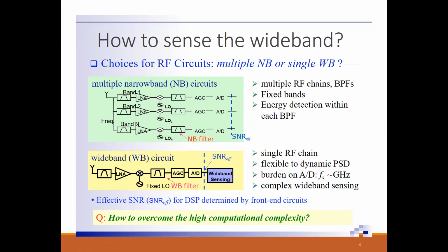You get my point. Even though the user is actually occupying 1 megahertz bandwidth, you think that 2 megahertz of bandwidth is occupied because you are using fixed bands. These filters are not variable. You check for 0 to 1 and you check for 1 to 2, but you are not adapting. So if a particular user is occupying from 0.5 to 1.5, that will induce the spectrum decision both here and here, which is again ineffective.